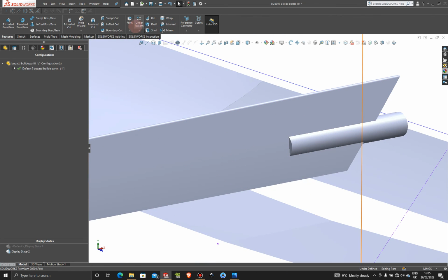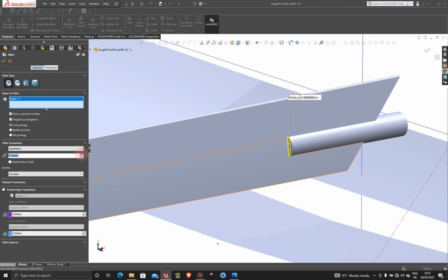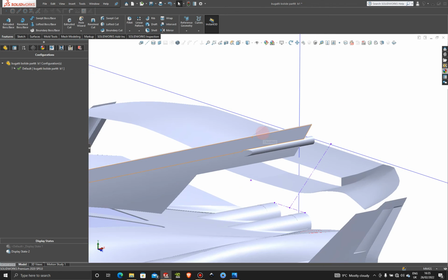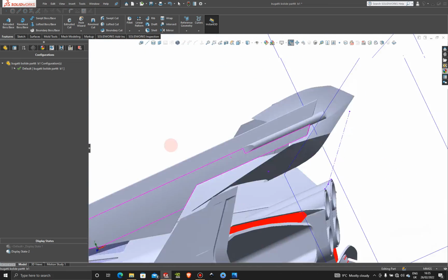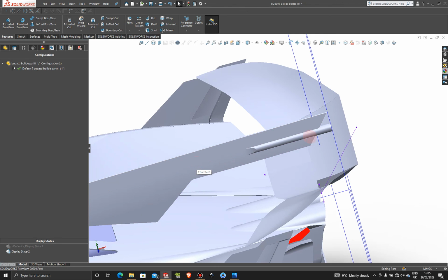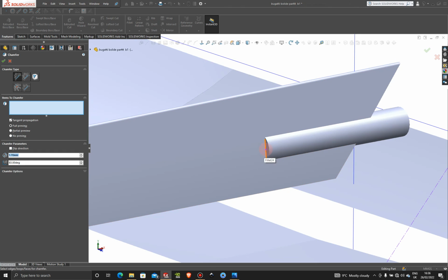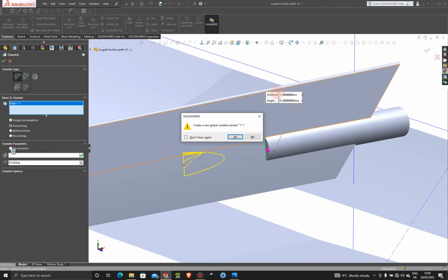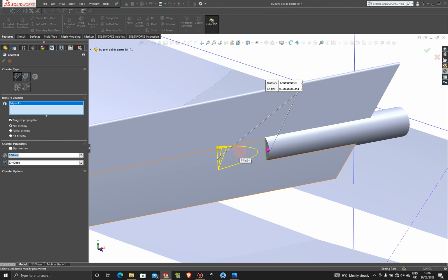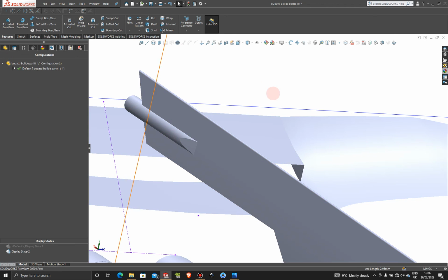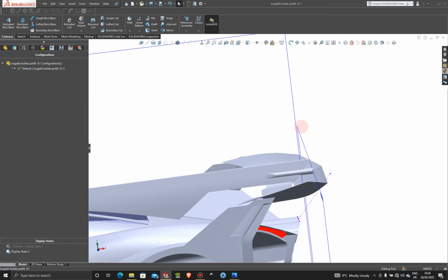And one more thing left to do here is we're going to add some nice fillet on these inner edges here. Make that just 20. Control Z, I think that's a little bit too much. So let's go again, and instead let's choose a chamfer. And let's choose this inside corner here. And let's just select one. Not global one, but one. And let's select on both sides, hopefully it does. Okay, that looks a lot better.